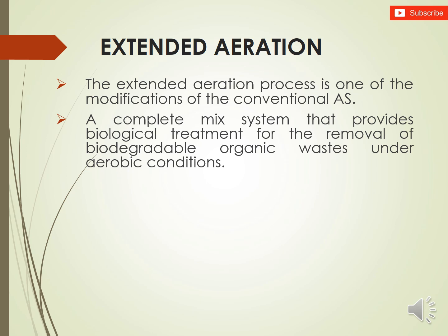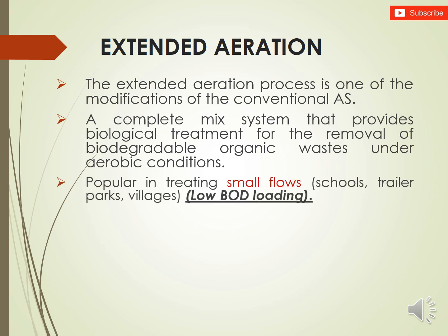Okay, this system is a complete mix system and provides biological treatment for the removal of biodegradable organic wastes under aerobic conditions. Almost same as conventional activated sludge, but there are some differences. As we said just now, this is popular in treating small flows like schools, trailer parks, villages, and which has low BOD loading. Okay, this is one of the conditions. So it has to be a small flow and low BOD loading.